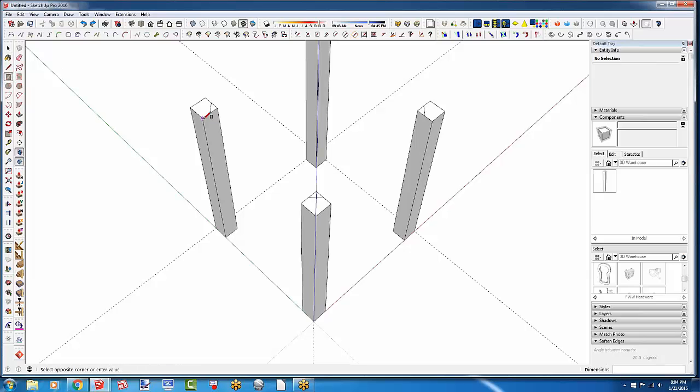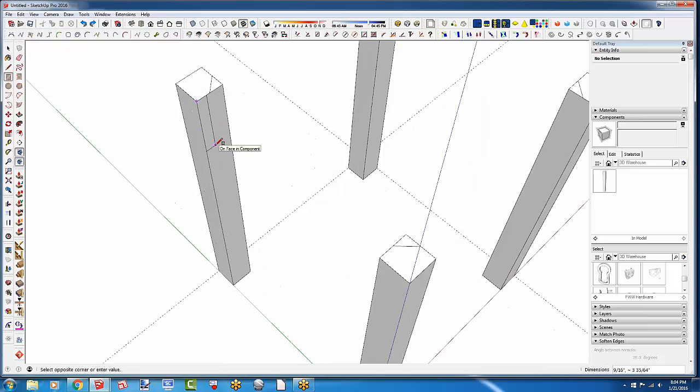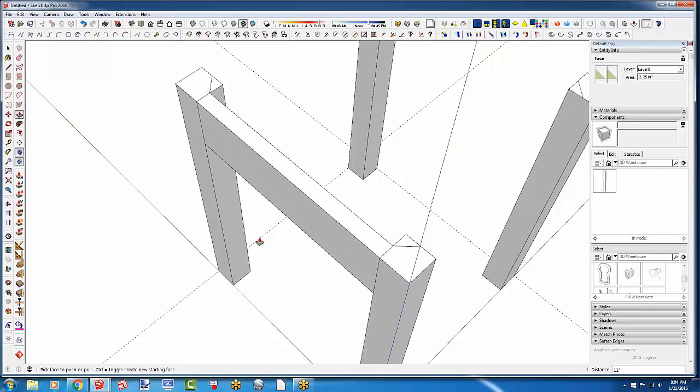Well, do we care? We don't really care at this stage. What I've done here is I've dragged out a long skinny rectangle, and I look at the dimensions in the dimension box in the lower right. I see the small number is first, so I know I'm going to type the thickness followed by the width. And how long is it? I don't care. It's that distance.